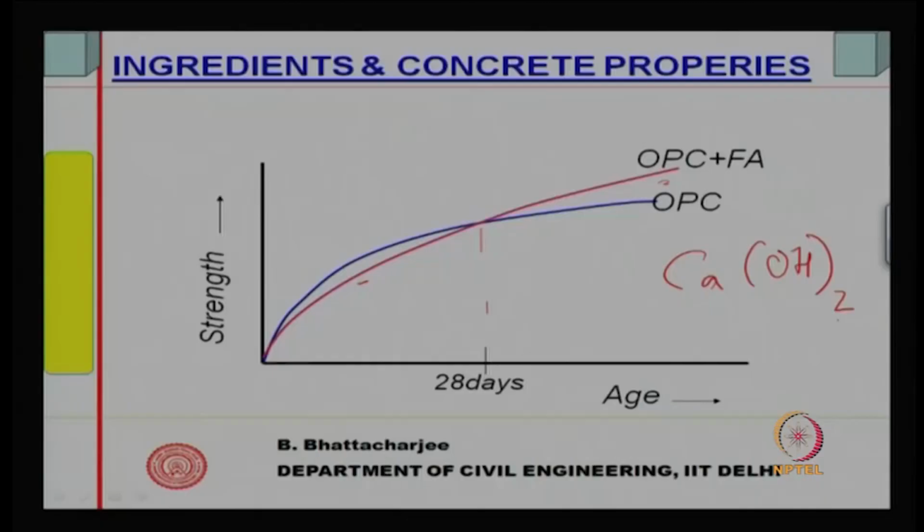Whereas with a cement water system you can simply demold it after 24 hours, here for 48 hours you do not demold and you do not test for strength. A cement system you can test for strength even after 24 hours or 3 days, but here you test it only after 8 days. Therefore, it shows that the reaction process is very slow. That is one effect. So, A, reaction rate is slow.